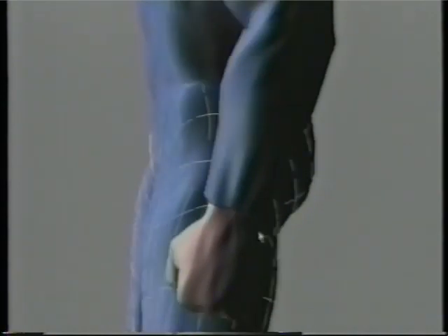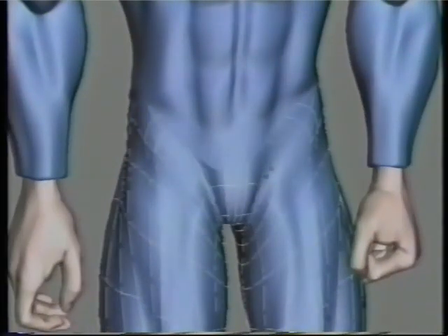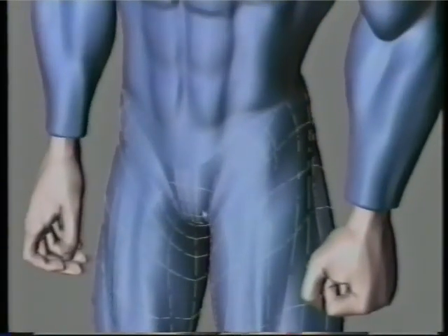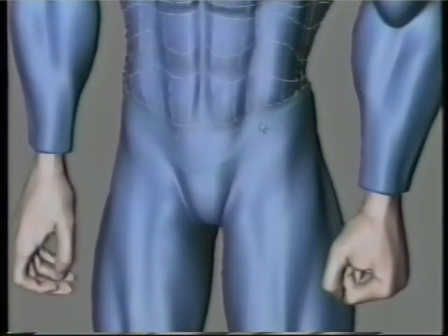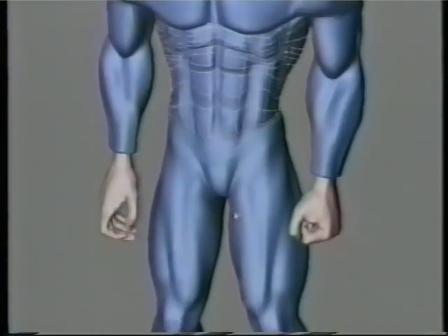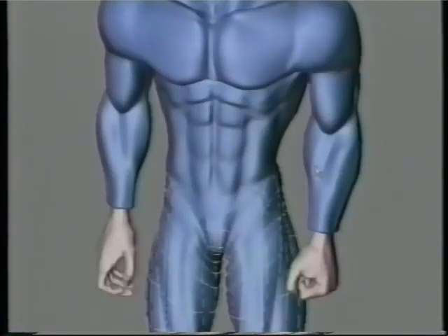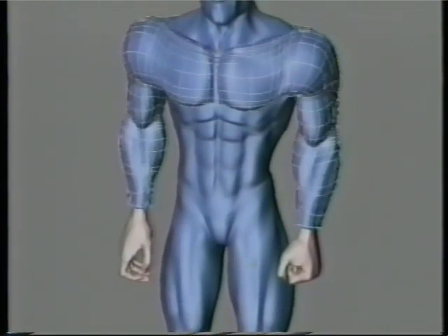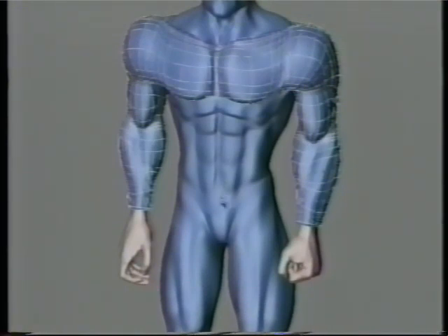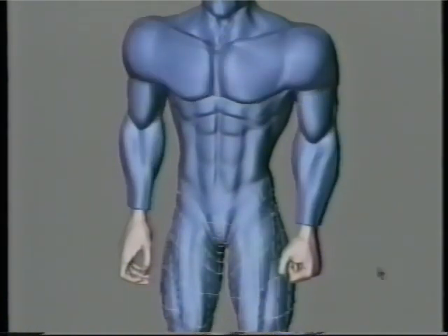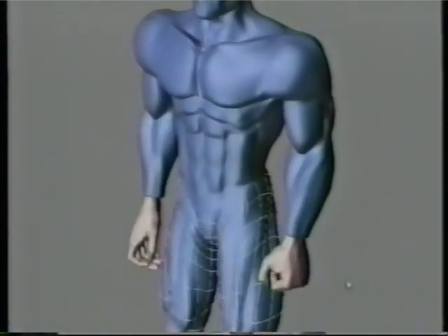This is a good way to make sure that these crease areas won't come apart because they're the same surface, and then the abdomen area is connected on with a surface connection technique. So the arms and the legs in this case are similarly designed to put the areas of stress in areas where there isn't a connection. Again, with the shoulders there's a clean area, and right around here it's one continuous NURBS surface, so there's bound to be less problems than there otherwise would be.